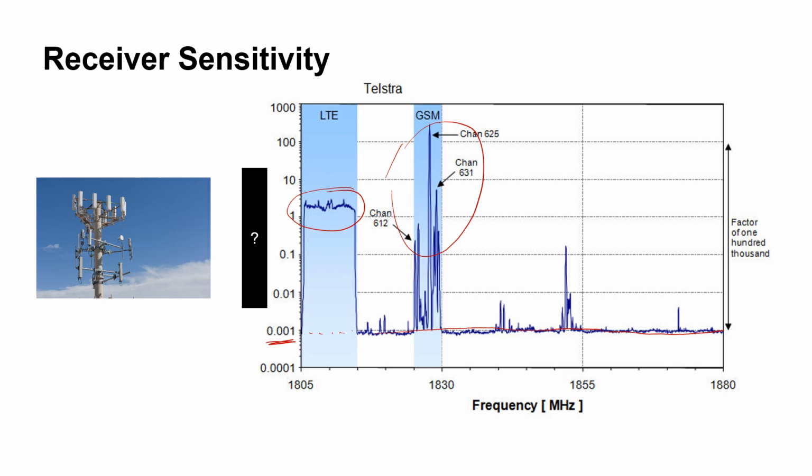So the minimum receivable signal is actually defined at the input of the receiver, not at the output. So this signal is at the input of the receiver. Perhaps there is a possibility that after passing through the receiver, and after the amplification and everything else, we may get this received signal to be detectable by whatever is coming after our receiver, that is generally analog to digital converters.